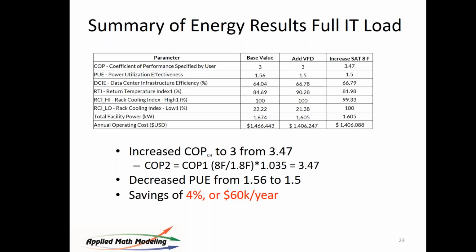Can you explain how to do the same procedure for raised floor design? This was a raised floor design. So they're all the same. I think you might have meant non-raised floor. The methodology is exactly the same. You lay it out the same way. You first try to get your air balance in position. Once you've got your air balance in position using the new VFD controls, then go ahead for your supply air temp and try to move it up a little bit.